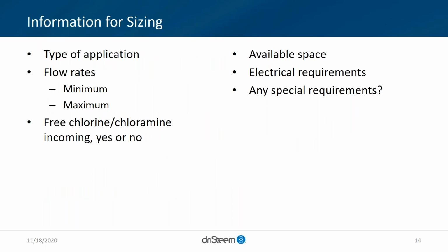Some information for sizing so we can help any end user on this call or any engineer or representative on this call: what's the type of application? What are the flow rates, minimum and maximum? Again, we talked about contact time. We want to really understand what we need to treat. And the biggest yes or no question is, is there chlorine or chloramine present? That's the main purpose. So if that's not present, obviously we need to talk about what that water treatment need is.